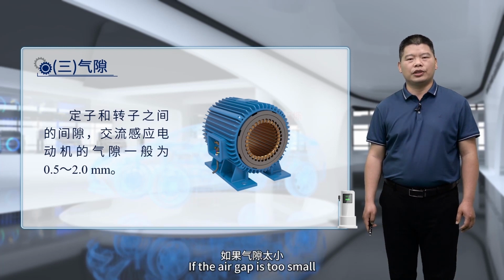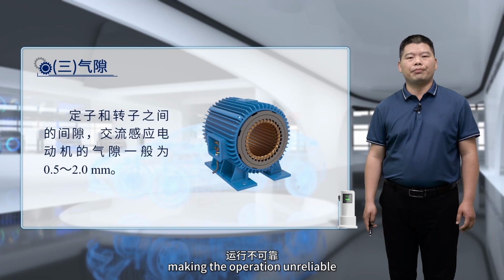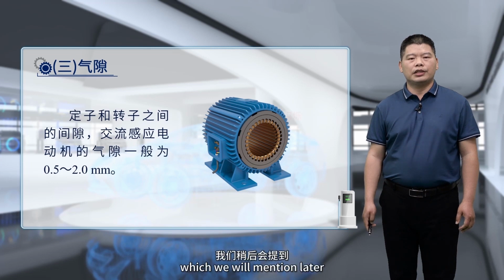If the air gap is too small, it will make motor assembly difficult and decrease the starting performance, making the operation unreliable. If the air gap is too large, it will cause a decrease in power factor during motor operation. The concepts of air gap, composite magnetic field, and electromagnetic torque, which we will mention later, are closely related to the air gap.